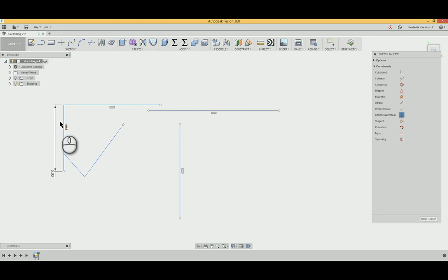You're going to have designs occasionally where you draw something, and it's kind of at that 45 degrees, and you want to apply a constraint to it. Take a sec, move it to the direction where you would like it to be, and then apply that constraint. Then your sketch won't go crazy on you.